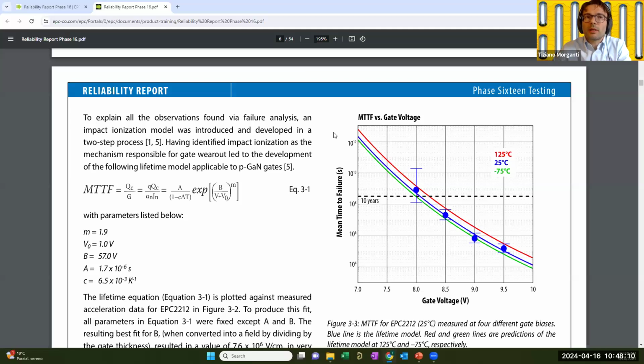So it is important to check the gate voltage signals against over voltage. I have to say this test here is done with continuous DC voltage on the gate. In case of transients, the duration of the stress is much more limited. So most likely this lifetime estimation here is much more pessimistic compared to the real case. So I hope to have replied to your question.